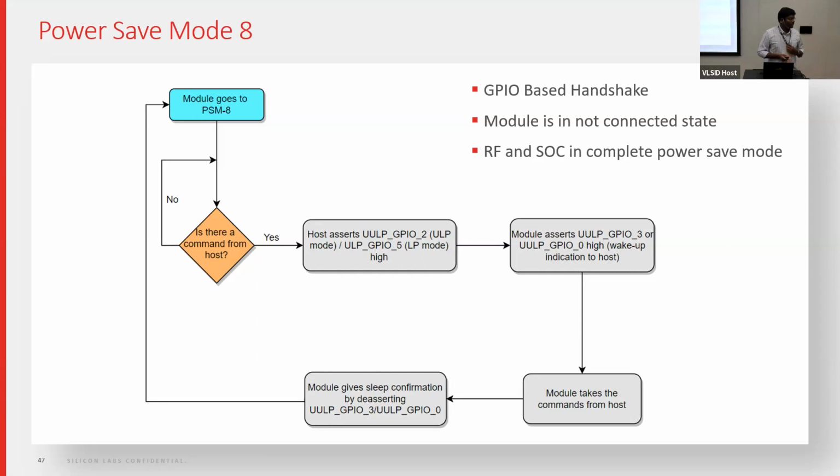What if a module is not reacting? Will you wait for some time, or a delay? How do you take that part into account? Right. If, for example, we have given a command and there is an error, the module is not accepting it or something like that, then we have to reset the module, power on, and then start again.